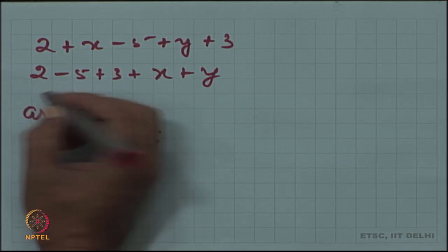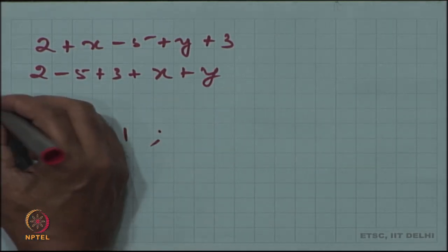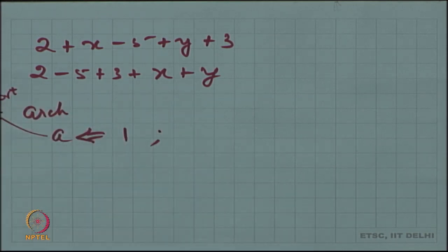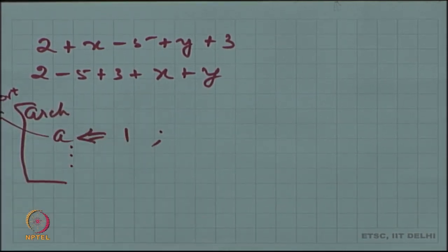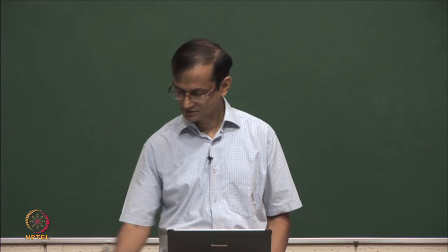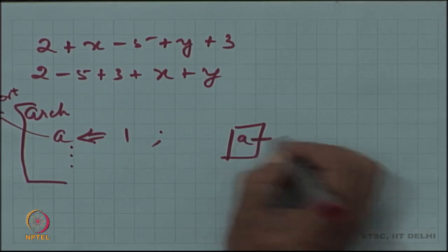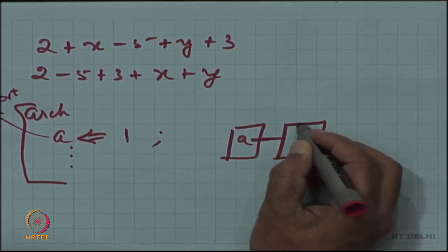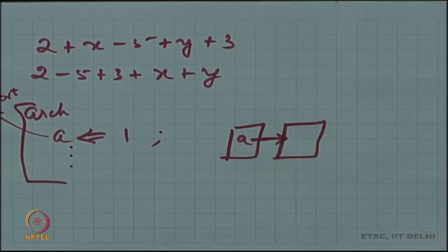So, let us have a port. So, this A is actually a port for us, and I did A equals 1, and I have some other things, and that is my model. Is that statement redundant? But if it's an output port, then it's an input port for any other entity, and I'm not reading that input port anywhere in that particular application. It is an output port from here, and it does form an input port to some other entity, and I'm not using it in that other entity in any way. Therefore, can you throw out this assignment?